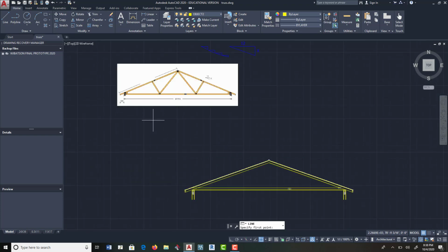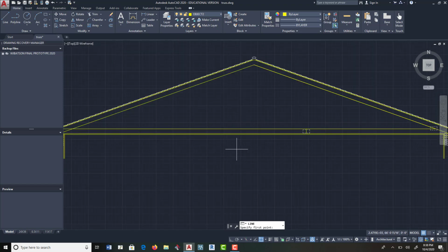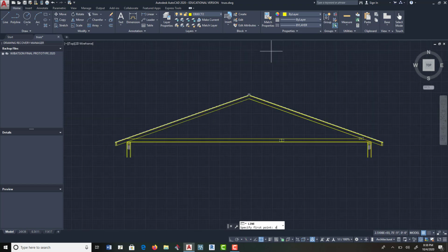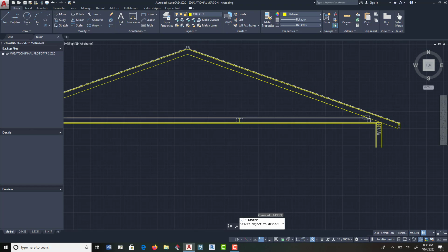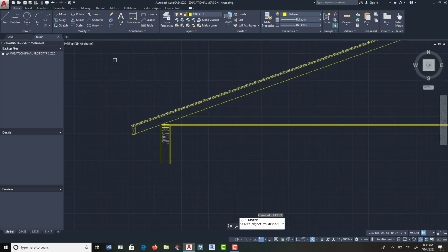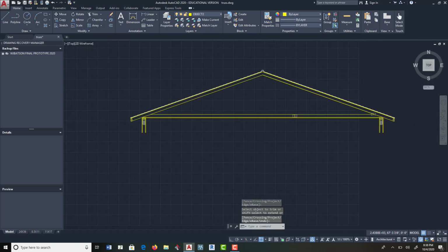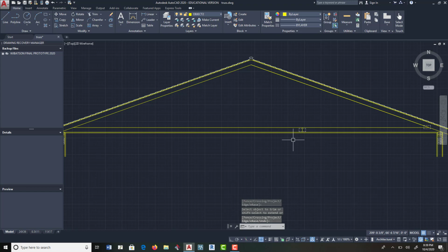So now we're going to get the third and a third and a third. So 1/3, 1/3, 1/3. So we're going to divide like we've been doing. Okay. D-I-V-I-D-E, divide. Okay. And it always tells you to select a line. So what line do you know is in 3s? So remember, this line is cut here, and it's not cut there. So if you're going to have an equal dividing line, don't forget to trim this piece off. Now you can divide that line, that top line. D-I-V-I-D-E. Enter. This line, type in 3, enter.